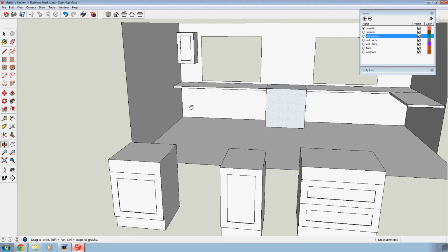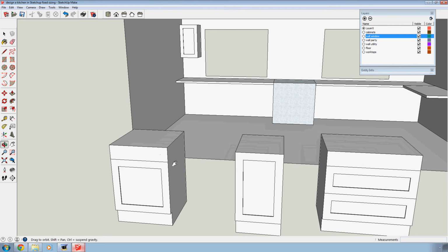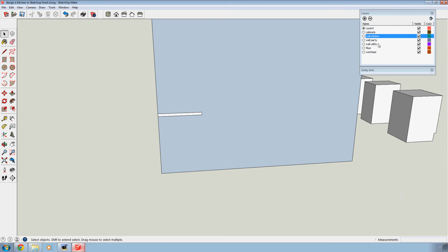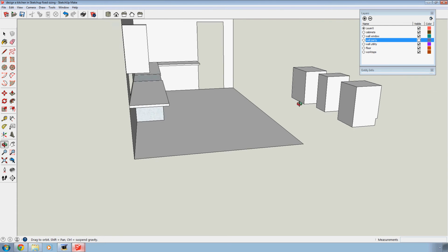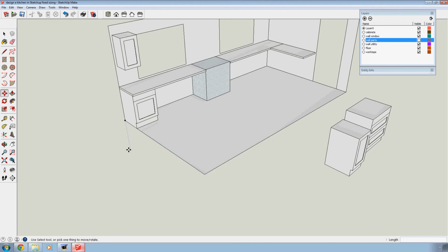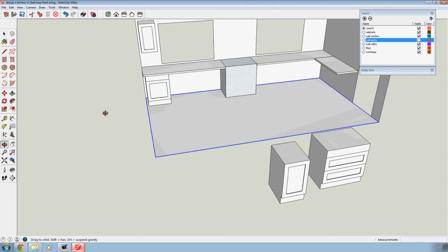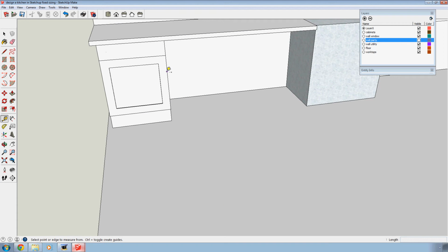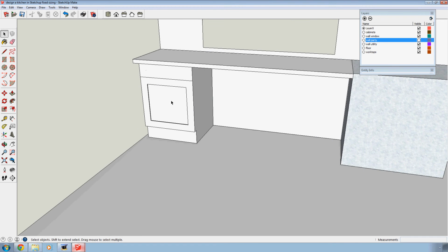Press the delete key, and now I'm going to put a highline unit in the corner again by, let's take the party wall off, and that's the highline unit. Let's move it into position. Move it out 50mm. This is currently 600 wide, and need to make it narrower.